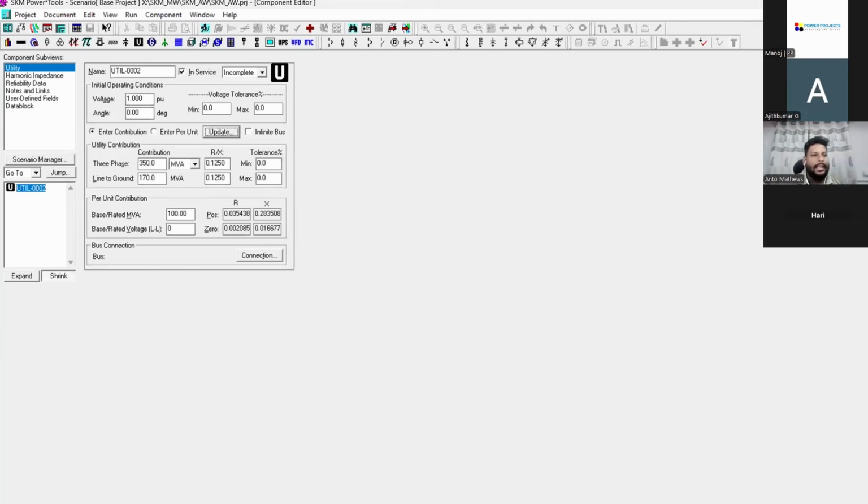Once I have updated correctly, my data will give no errors. If I put in any wrong numbers, or my modeling has not converged or has any problem, it will give me a one. You can find it in the endpoint; there is one column which shows the calculated zero sequence impedance is negative, meaning my parameters are not properly aligned. Once I have the parameters right and click update, my system will not have any warnings or errors, right?